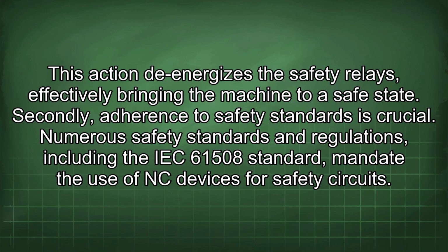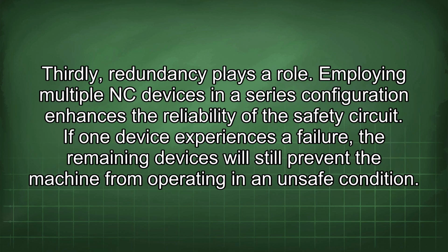Secondly, adherence to safety standards is crucial. Numerous safety standards and regulations, including the IEC 61508 standard, mandate the use of NC devices for safety circuits. Thirdly, redundancy plays a role. Employing multiple NC devices in a series configuration enhances the reliability of the safety circuit. If one device experiences a failure, the remaining devices will still prevent the machine from operating in an unsafe condition.